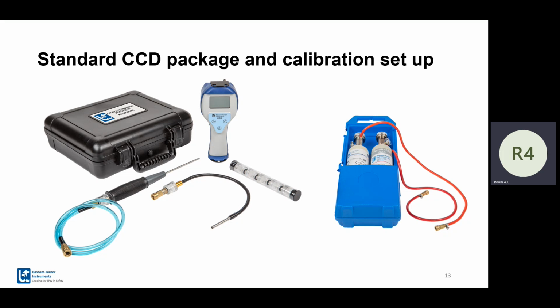We know how long it lasts at our utility customers who are calibrating every 30 days. We use about half a liter of gas per calibration. Just to give a ballpark, this bottle has 103 liters. We use from half a liter to a liter for calibration. I won't say exactly half a liter. So you take that number and figure out how many calibrations you can do with it.